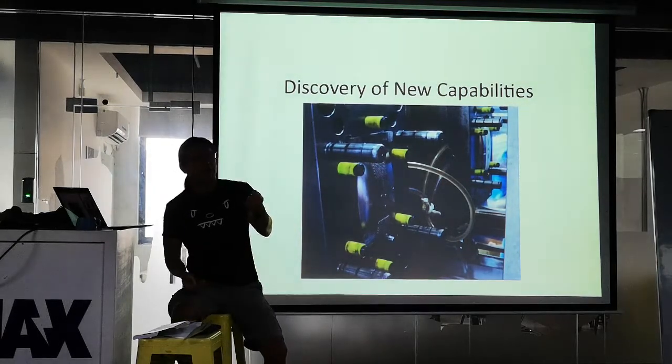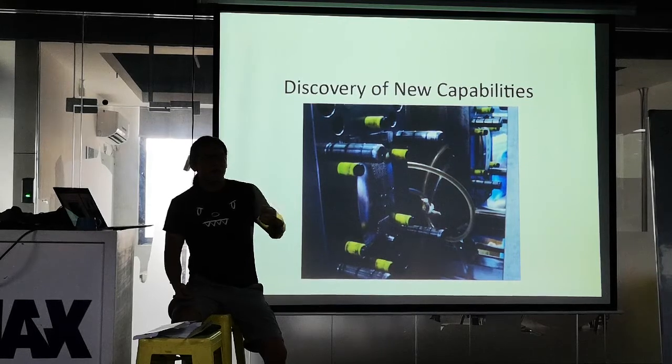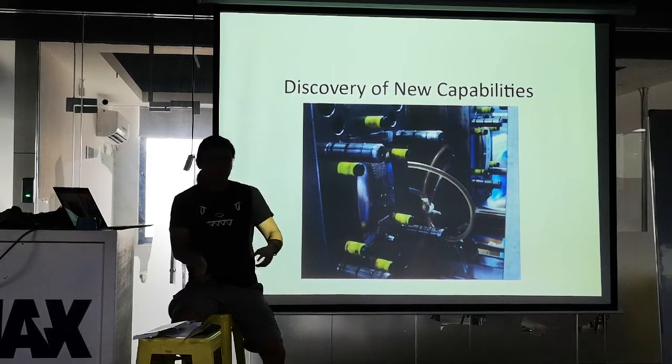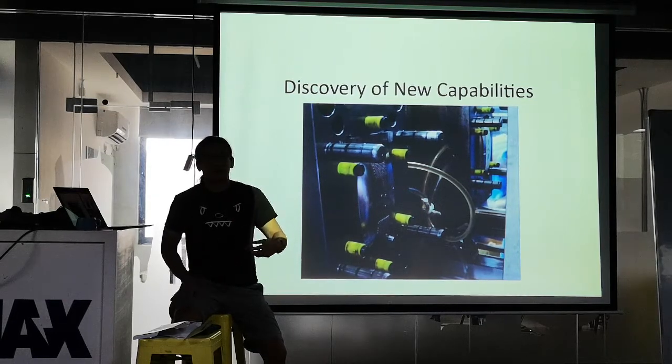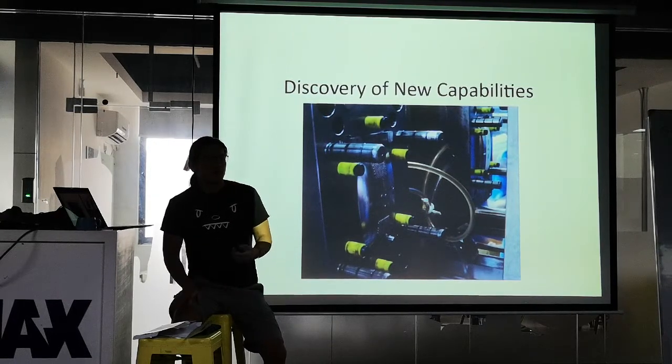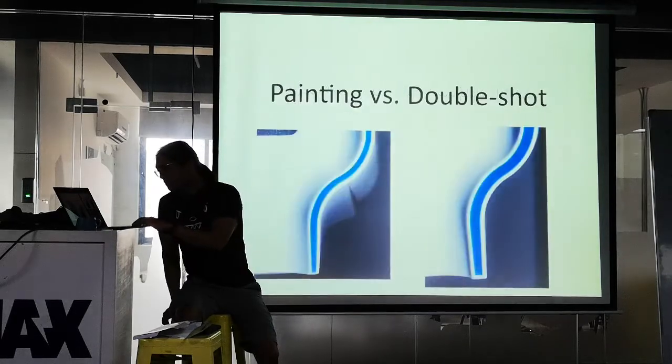Victor had some non-waste product that he showed with the elastomer. That one is done manually. They put the hard piece in, they get the hard pieces out, and then in a separate step they put them in a tool with the soft pieces. They put the soft piece over. You can do that if the tolerance is pretty big on your elastomer step, but you're going to have a little more tolerance issue if you don't have the rotating tool.